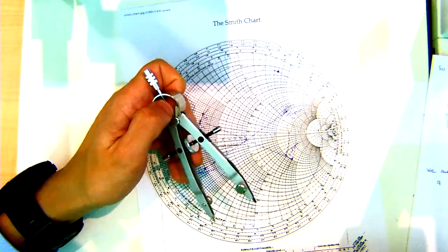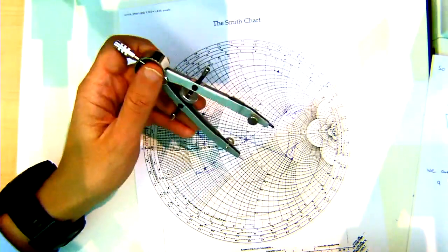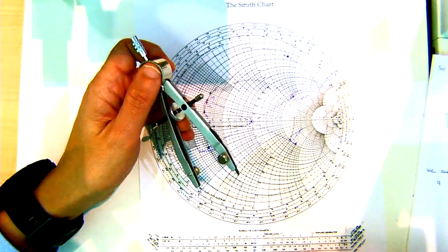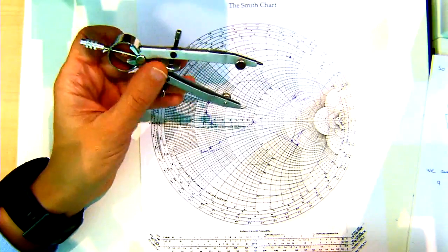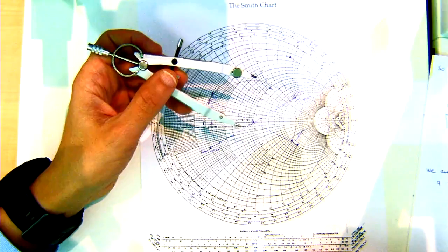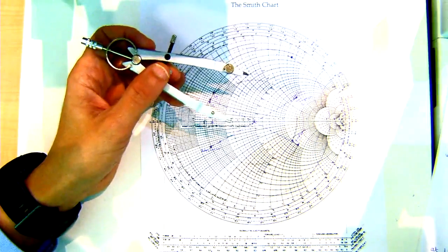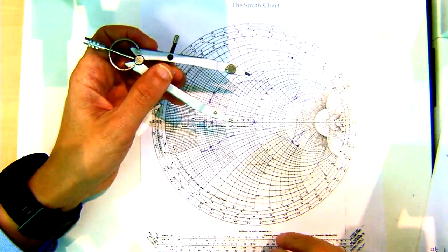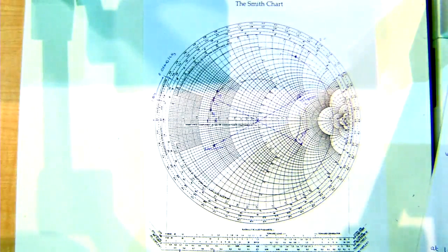For solution 2, because it's a much larger length of line, your gamma is 0.85, so it's much more poorly matched. Therefore, if you were building your system to operate from 2 gigahertz down to 1 gigahertz, you'd choose solution 1 over solution 2, as an example, because it's got better matching over the frequencies of operation that you want.